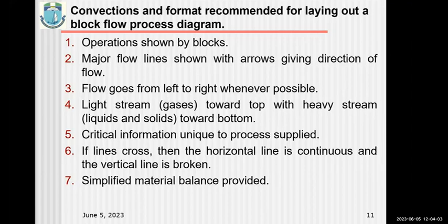Normally too, if there are light streams, it's usually done up, with the arrow facing up. If you have heavy streams like liquids and solids, the arrow is usually at the bottom. And what do you also do on that block diagram? You also provide some critical information. For instance, you may need to specify the flow rate, the temperature, and if there is need for it, you may also state the concentration or the pressure.